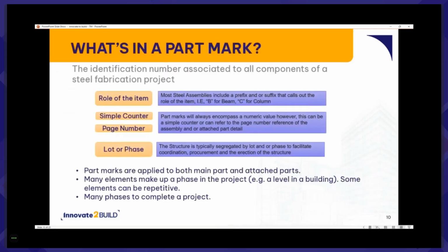Now, the identification numbers are hypercritical. They're very important for sorting data, not only for the understanding of what needs to be fabricated, but later on when executing other tasks like truck loading or creating your fabrication orders. Delivery notes, invoicing, any task like that, it all correlates back to the identification number. So this is a very important component to organizing the information and being able to communicate back to the general contractor or internally where components are at all times.